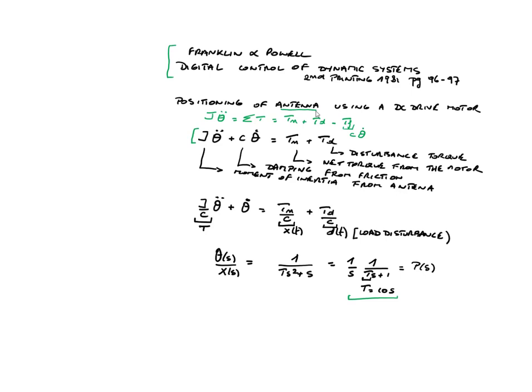If we divide by c, we obtain this equation here, and you can compute that this is expressed in seconds. This will express a time constant. What we'll use as input is the net torque over this c to make everything easy from a notation point of view, and this disturbance torque divided by c will be the load disturbance, and we have called it, I think, W at the beginning of the course, but it's sometimes also notated like this.